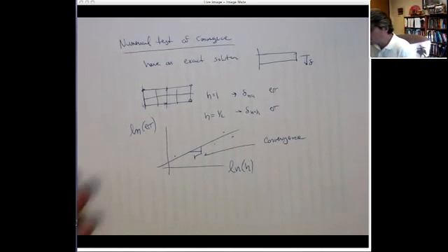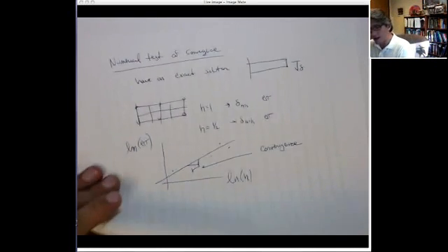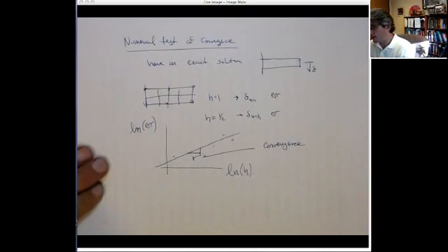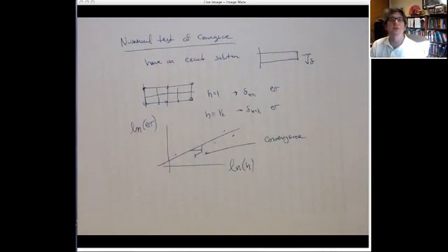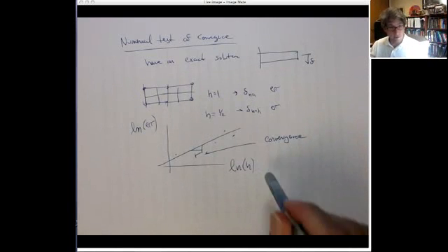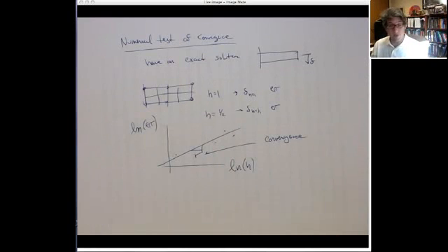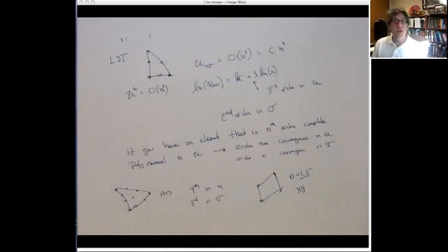You can actually also do this if you don't have an exact solution. And this gets into this concept of a Richardson extrapolation, and it can give you a guesstimate on your error. And I think actually I'll talk about that later. So in the homeworks, when I ask you to check the convergence, this is what I'm asking you to do. And you should be able to check that the convergence you get experimentally through the finite element results matches the theoretical ones. Okay? Okay, that's it. Let's stop there.